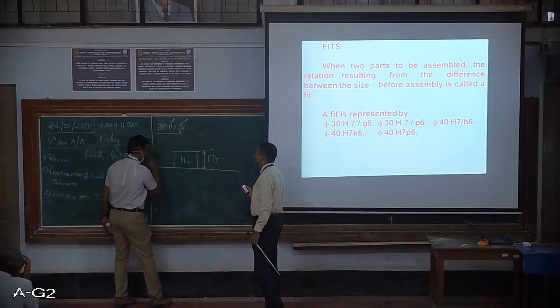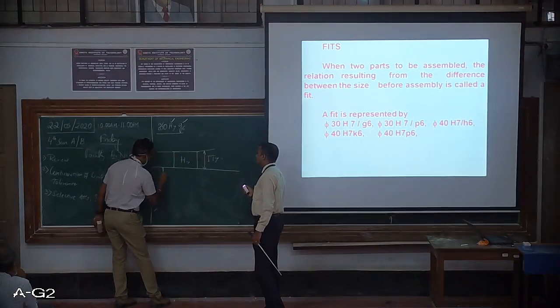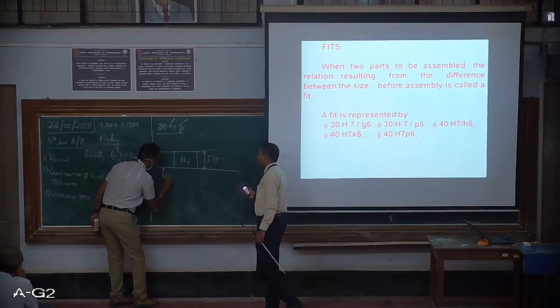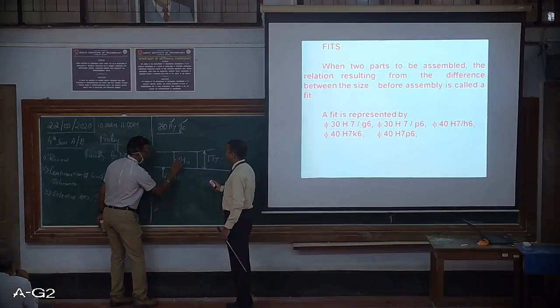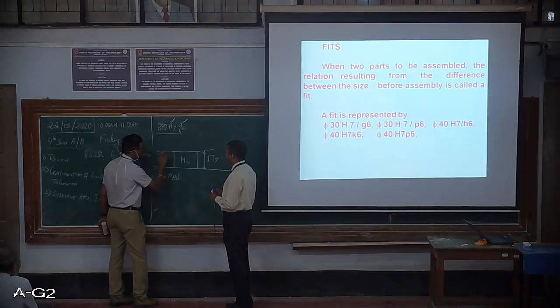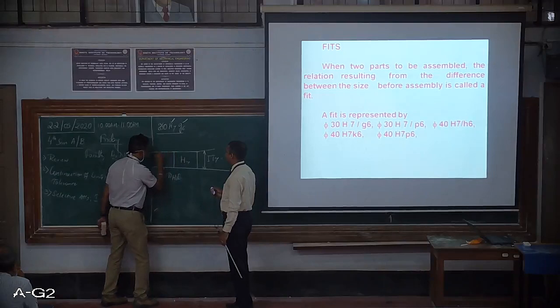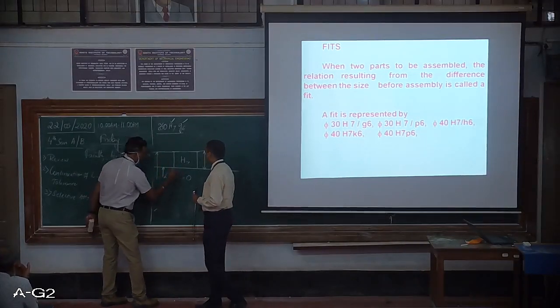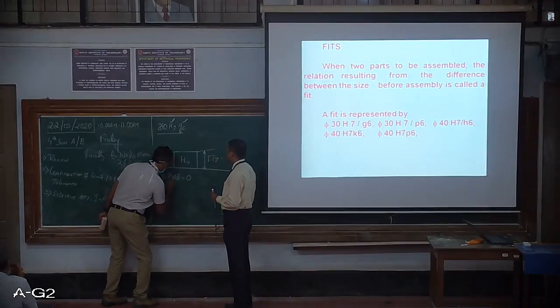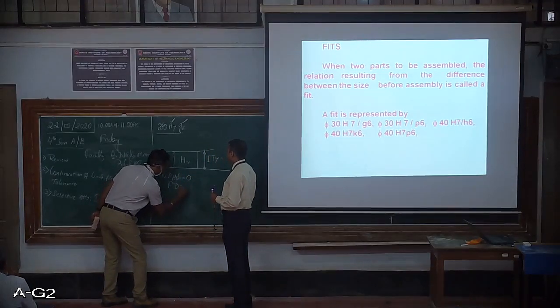Next, this is the lower deviation of the hole. This is the upper deviation, which is equal to 0. Fundamental deviation is also 0. FD is also 0 here.